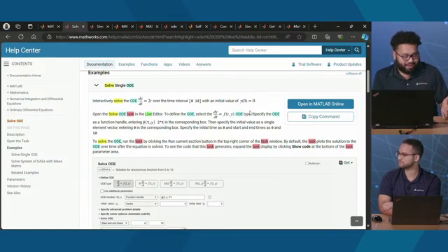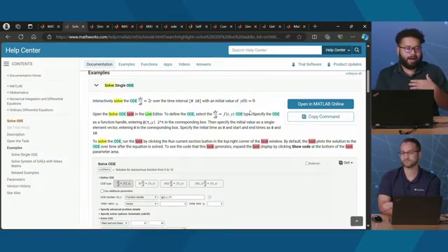I'm sure you can make a digital twin in MATLAB. My recommendation would be to use Simulink for that, because the big thing with digital twins is you have to have that notion of time. When you're running a simulation, you have to be able to step through it and move forward in time. With MATLAB, a lot of that you'd have to write yourself, but Simulink is built for that. You say, okay, here is my function.